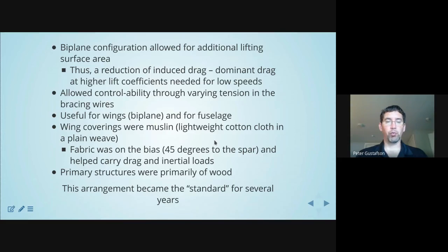Now, in this case, wing fabric was actually structural. Okay, you might not think of it that way. It's membranous. Recall we talked about structural classification last lecture. We said cloth tends to be membranous. It can carry tension well. In certain circumstances, it can carry shear, and shear and tension are related to each other in a very direct way, as I will teach you a little bit later in this class.